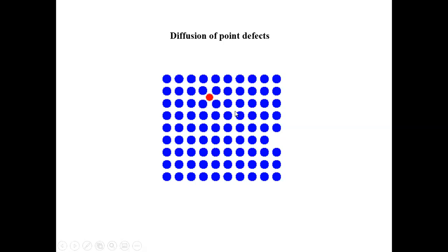Because if you look at the way they move around, it's pretty much random, right? So this is what we call solid state diffusion. Because in a real material, especially in an alloy, you always have these different types of point defects. And these point defects at finite temperature are allowed to move. And the way they move around is through diffusion. And as you can probably imagine, if I increase temperature, their motion is going to be more and more active.